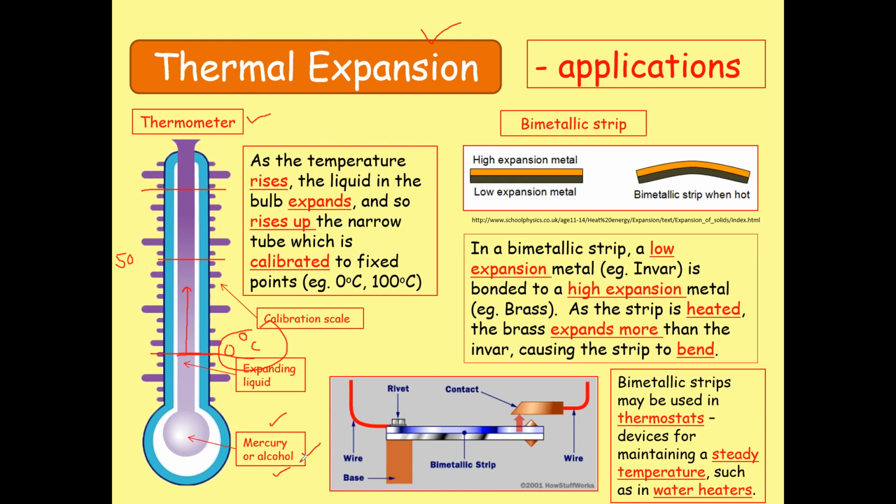If we have a little bit of alcohol, we use a glass capillary. We make a glass capillary bulb at the end. We close off that end, and we may even leave the other end open, and we simply put that glass capillary in ice cube water, and we can mark the lower level of the alcohol as 0. And once we start heating that beaker up, the upper level can be marked as 100, and then we can calibrate it as a temperature, right, as a thermometer. So we can literally build our own thermometer in the lab.